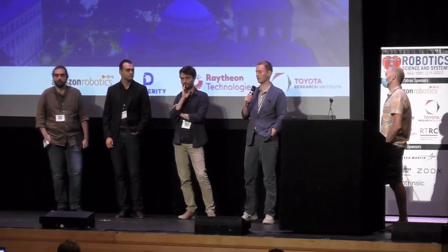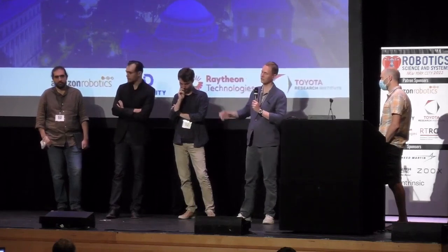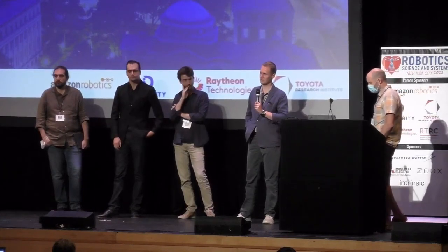For parameters that you don't have full control over, our framework includes a distinction between design parameters, which might be the weights of a neural network that you can freely change, or the mass of a link in your robot, and exogenous or environmental parameters. So we include a method for handling these uncontrolled parameters in the environment. In the example that I showed, the uncontrolled parameters included the mass of the box, the initial position of the box and the robot, and the coefficients of friction of all contact pairs. Those were assumed to vary according to different distributions, either uniform or Gaussian. So we include the opportunity to bake those uncontrolled parameters into our framework, because it's definitely important to account for what you can't control in the design process.